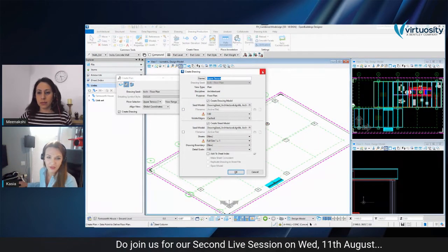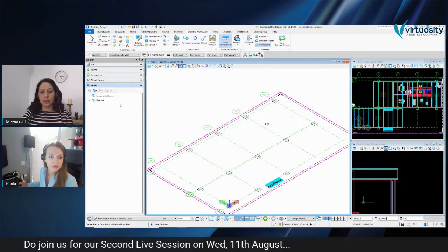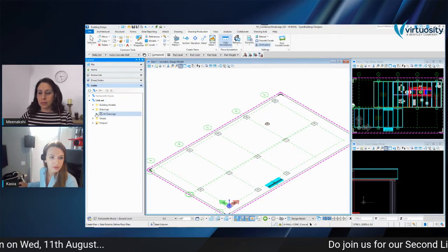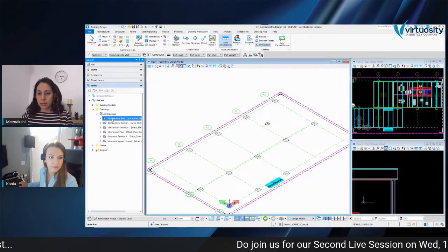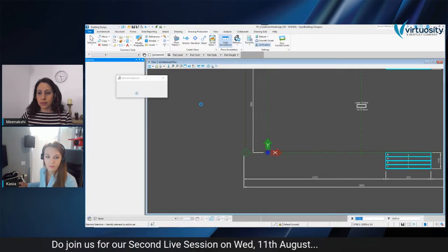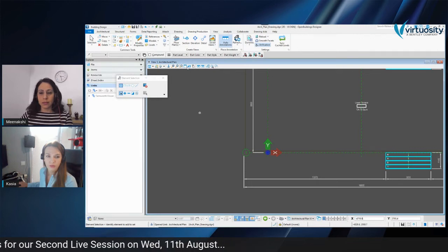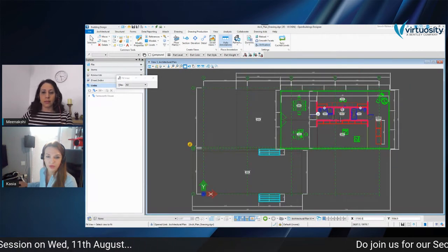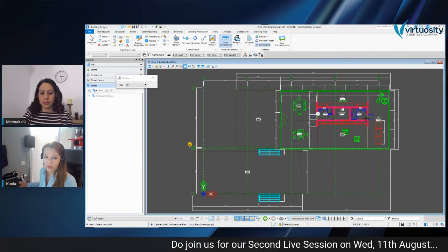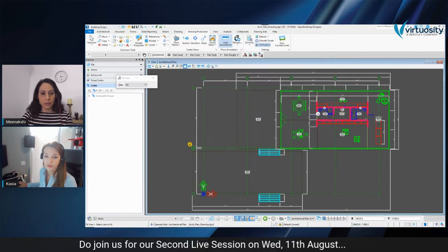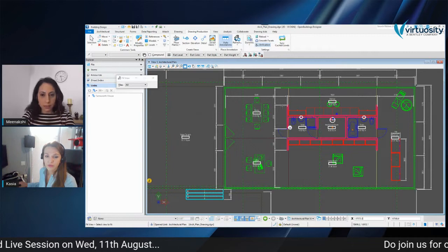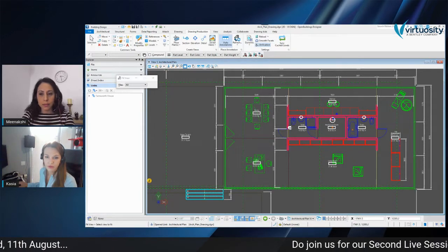now if I click OK, the drawings would be created, but as I have them ready, I will just quickly move to one of them, maybe the architectural plan. So I'm moving to the drawing file, which is the first one we work on after the creation. So what we can see here is a 2D drawing, and this 2D drawing is the saved view of our BIM model. So anytime we change something, it can be updated simply in this drawing file.